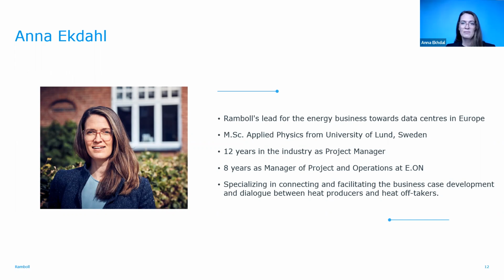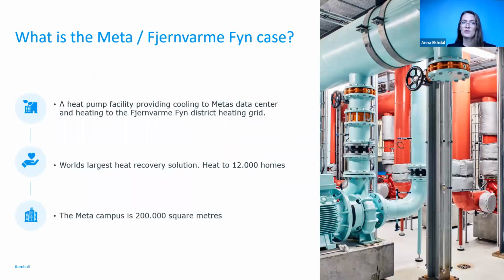So next slide, please. First off, what is the Meta Fjernvarme Fyn case? Well, it is a heat pump facility and it is providing cooling to Meta's data center at around 20 degrees, and at the same time, heating to the district heating grid at around 80 degrees. It supplies around 12,000 houses in Odense with heat. The picture on this slide is from the facility, and you can see the red pipes transporting hot water and the blue pipes transporting cold water.